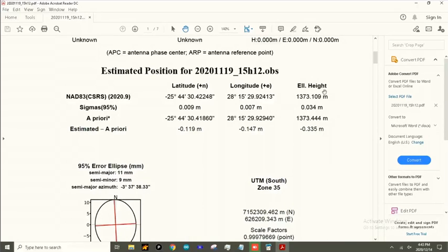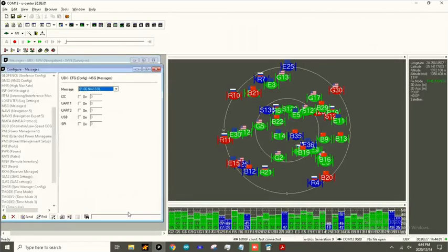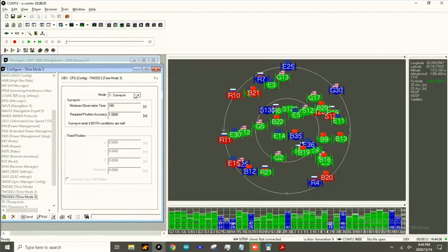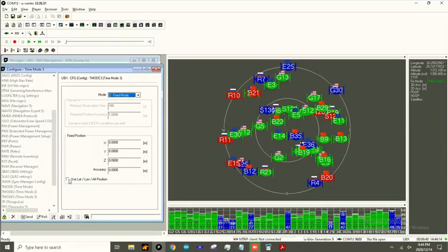So using these coordinates, they can either be transformed back into ECEF coordinates, or they can be adapted just in the current form with decimal places. And we can then go back to ublox, back to our configuration window, back to our time mode 3, and then we can say fixed mode and copy and paste those values in here using either ECEF or latitude, longitude, and altitude information.